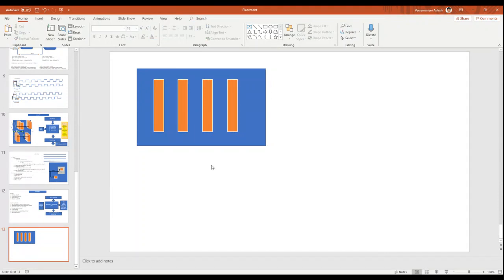So let's say aluminum first. Suppose it is aluminum, the manufacturing process used is called plasma etching or dry etching, wherein first they will put all of M1, all of aluminum everywhere, and then wherever M1 is not required, they will etch away.